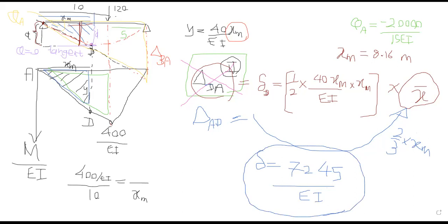So you will see this is not a very straightforward thing, right? You need to find where you get a zero tangent, a horizontal tangent, and zero thetas. So you need to be tricky. If you have varying loads, distributed loads, your bending moment curves will be curves. So taking the first moment of area and finding the area is not so straightforward, but there are simplified assumptions that you can manage.